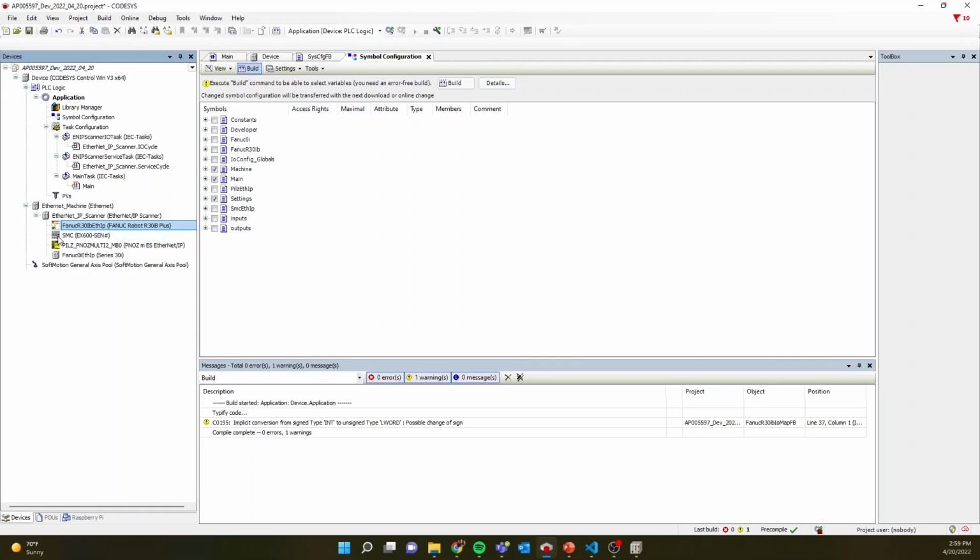For each one of the devices that we have listed, there's a certain frequency or RPI at which we want to read data, and when we decide to scan in and refresh our inputs and outputs from these associated devices, that's all happening here. This little program here is actually responsible for making sure that happens on time.